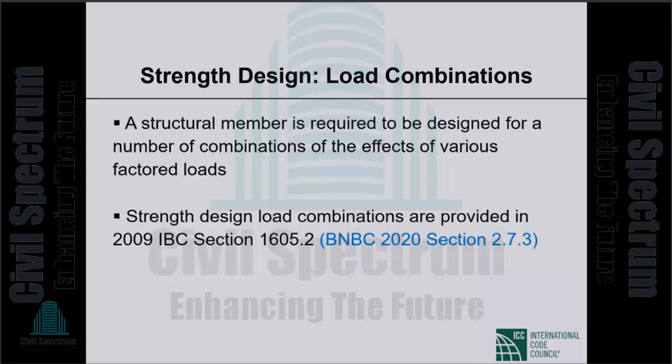We have service loads, service load effects, factored load effects, and then combinations of factored load effects, which is the required strength. Strength design load combinations are provided. Notice I did not even mention ACI 318.